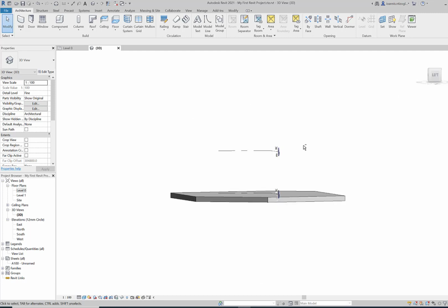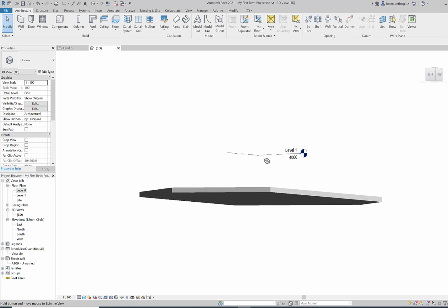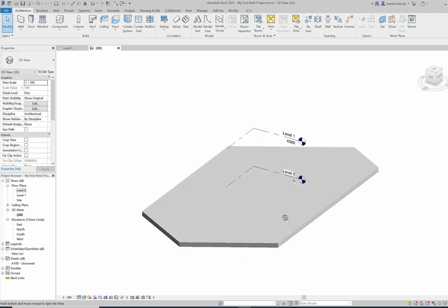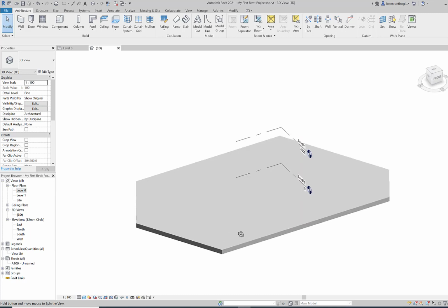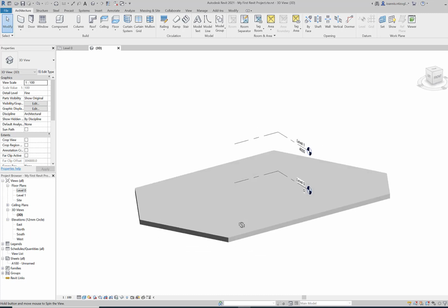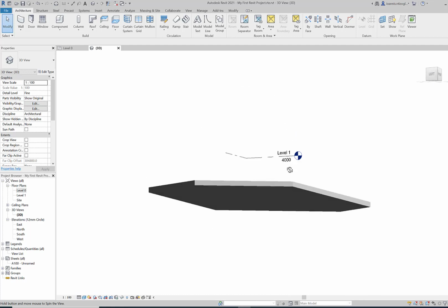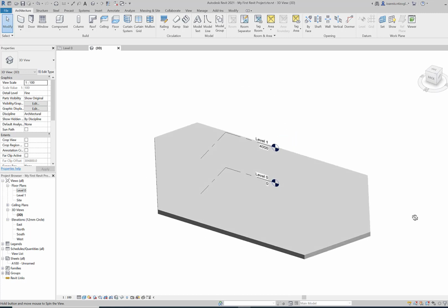If I hold the shift key down, my mouse cursor has a little minus icon. When you see this, then right click and drag. As you right click and drag, you will see the mouse cursor change to arrows going to the left and to the right, which indicates that I can move the object around. Okay. So now we know this.